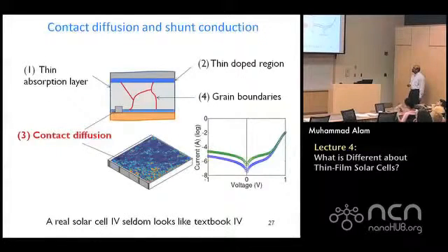So this is something I want to talk to you about next. And this has to do with this contact diffusion. What the contact diffusion will essentially do, in summary, is this: originally I had a PIN structure. The contact diffusion, localized in this place, will make this region P-type, because aluminum, when it diffuses in, will convert this region to P-type, and therefore this region will become a PIP structure. It will not remain a junction anymore.